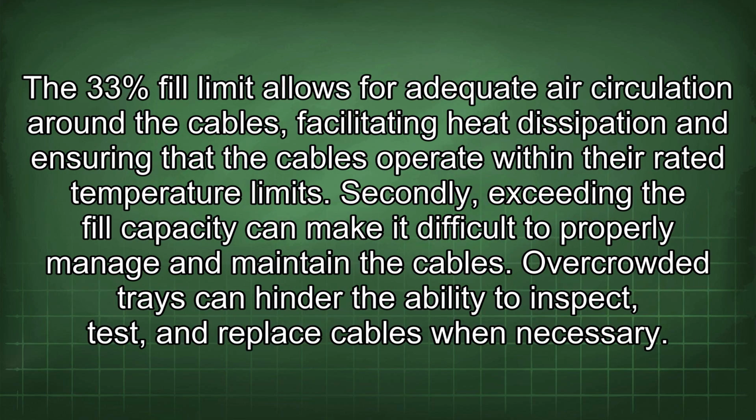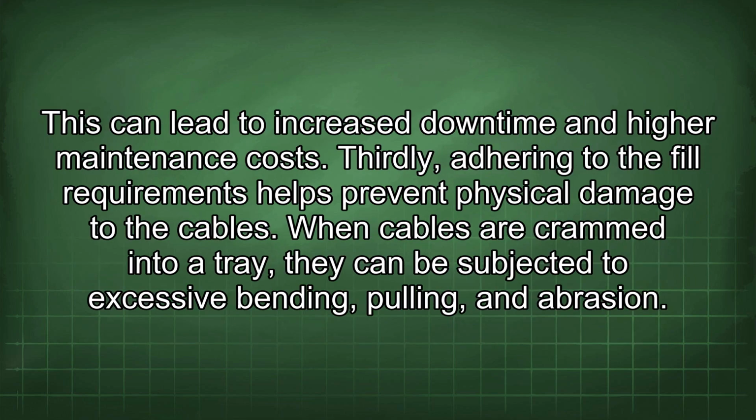The 33% fill limit allows for adequate air circulation around the cables, facilitating heat dissipation and ensuring that the cables operate within their rated temperature limits. Secondly, exceeding the fill capacity can make it difficult to properly manage and maintain the cables. Overcrowded trays can hinder the ability to inspect, test, and replace cables when necessary. This can lead to increased downtime and higher maintenance costs.